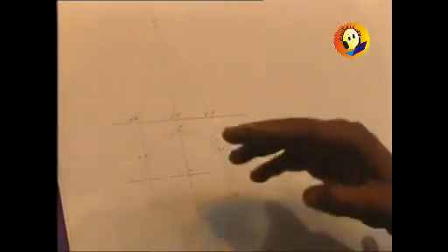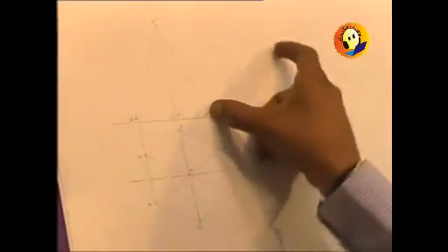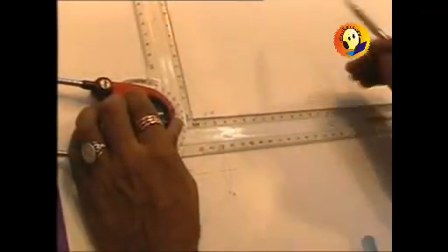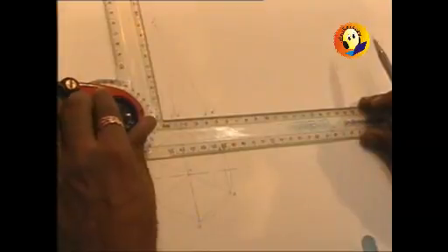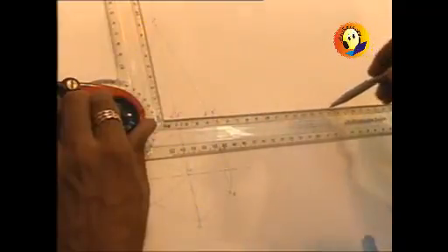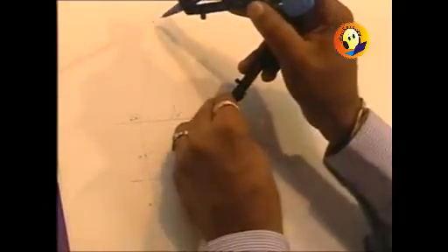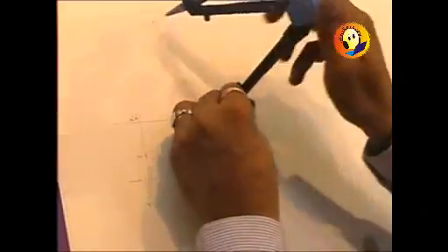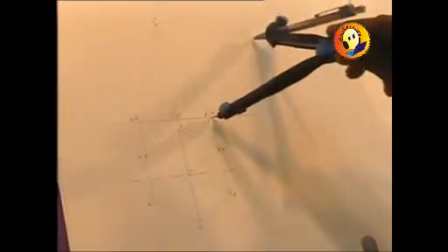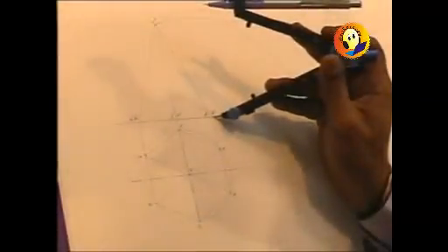Now we will be performing the rotation about point D', E', so that the V' point will be moved and shifted to the XY line. So let us first of all extend the XY line. The XY line is extended, and then we will perform the rotation with D', E' as the center, and up to V' will be the radius. Draw one arc. So we get point V' on XY.